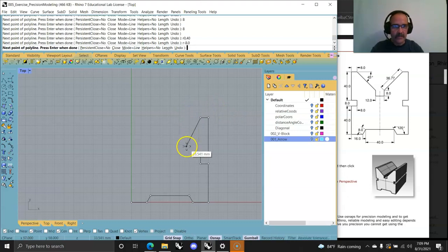And this is interesting because we're pulling it down at a 45-degree angle, and we are going to reference. Actually, I don't think we need the reference. We can just say comma, angle, shift, less than sign, 45 degrees, enter. And that's going to snap to 45 degrees, and we want that distance to be 36.77 because they gave it to us in the drawing. Now I can do down 8.